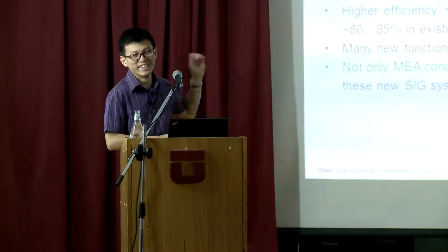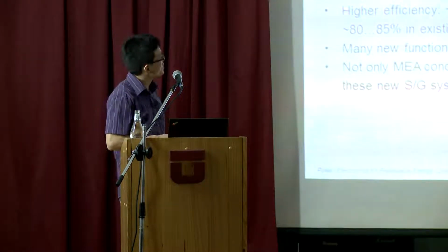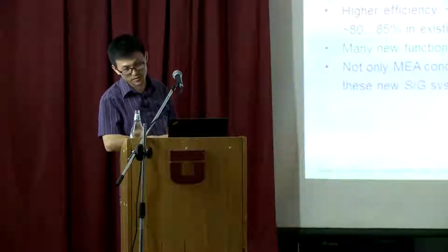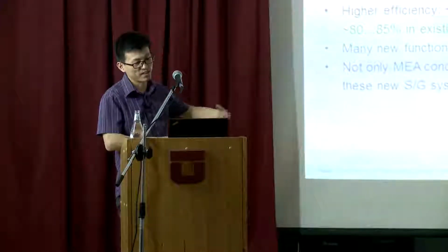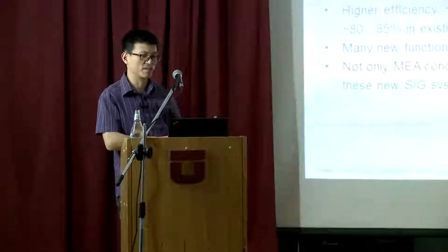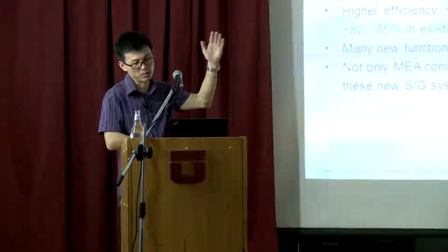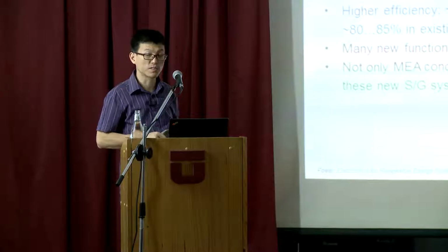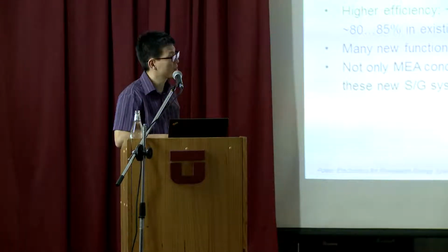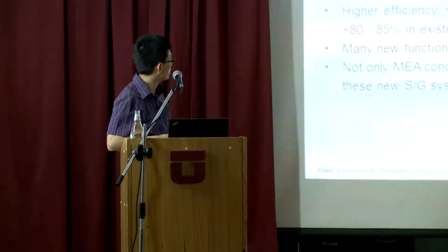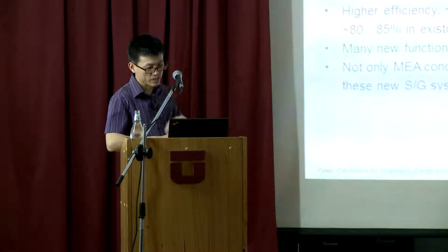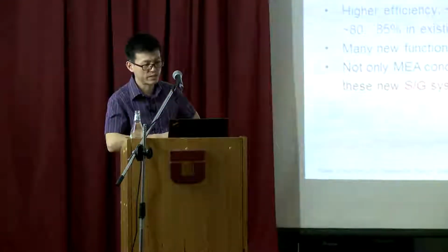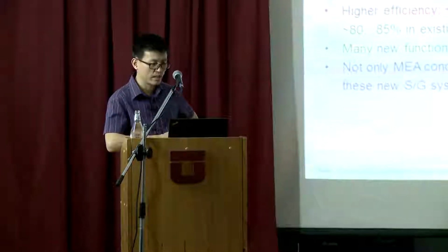So essentially it is a starter generator system for aircraft, and we mainly focus on generation, because most of the time this system will be used as a generator. Starting is a very short period of 2 minutes, and afterwards most of the time we'll be using it as a generator. The power density of the machine is about 3 kilowatts per kilogram. And the weight saving compared with the current technology in aircraft is about 20%, which is very, very significant.